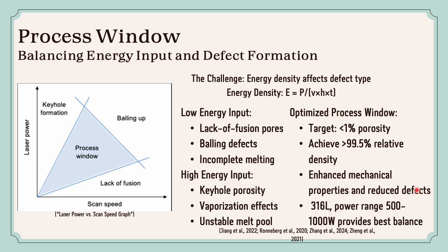For 316L stainless steel, studies have shown that a power range of approximately 500 to 1,000 watts often provides a good balance between the productivity and material quality.